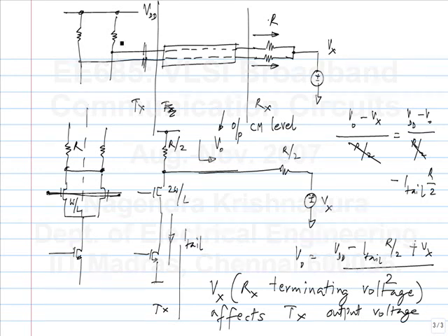Do we really need to transmit VOCM? No. So one thing is, if we use AC coupling, with the AC coupling capacitors on either the transmit side or the receive side, then Vx will certainly not affect the transmit output common mode voltage. That is one thing. What else can you do? Put the load resistor, this one, here. No, but you want a doubly terminated transmission line. I have not explained transmission lines and why we need all that, but I want termination to the transmission line on both sides.